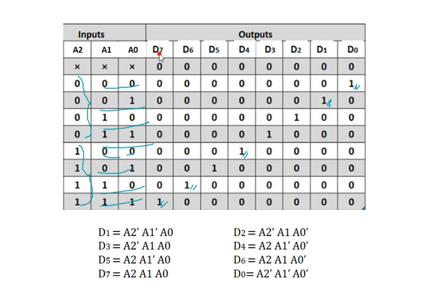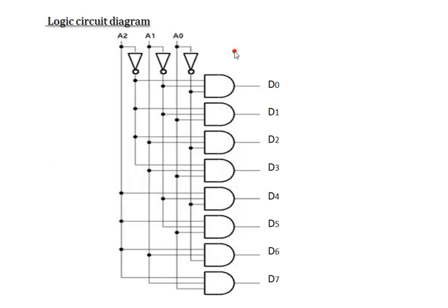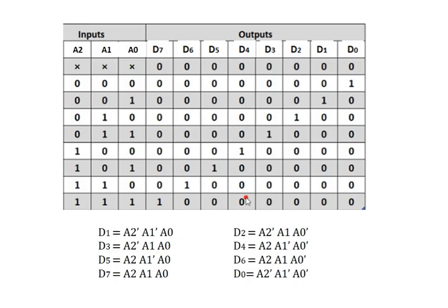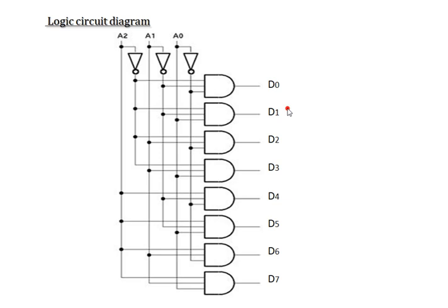For this I have written Boolean expressions for these output values. Next, this is the logic circuit diagram for the 3 to 8 decoder using two 2 to 4 decoders. Again, try this circuit based on these Boolean expressions. This is the second way of implementing a 3 to 8 decoder. The first way is direct implementation, and the second way is by using 2 to 4 decoders.